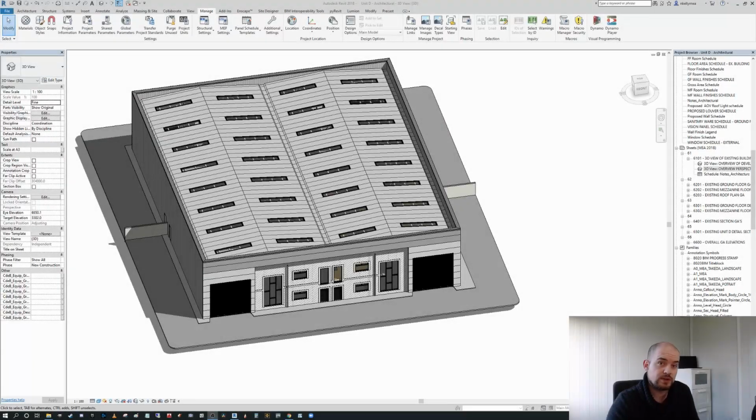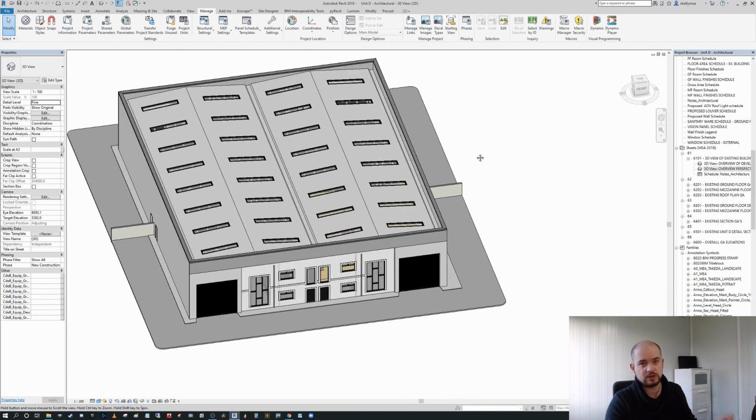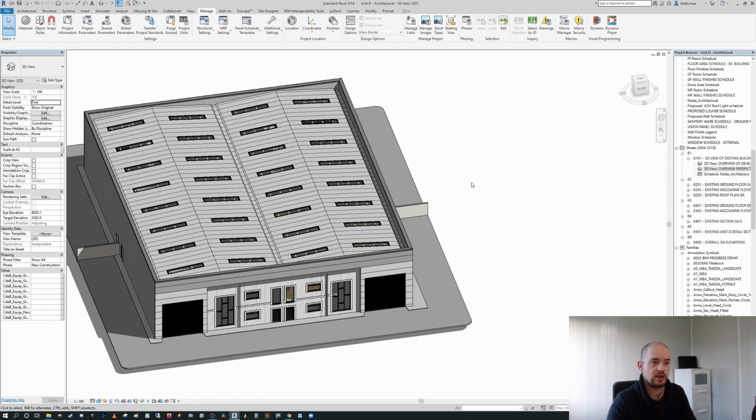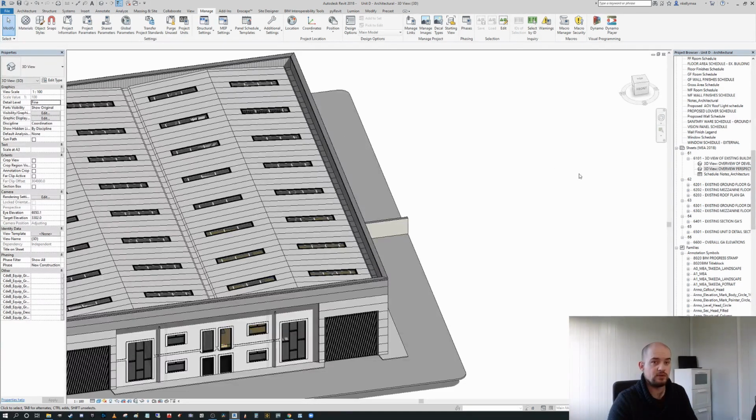Step 2, how to understand the directional drag selections of Revit. We all know that we can select by merely dragging a box in one way or the other. But I want to show you on screen here the difference between the directions of the drag and what they mean. If you drag from your top left to your bottom right, you get, by default anyway, this solid square. What this means is that this will allow you to select anything that falls within the overall boundary of what you're dragging. So the drag selection there, it's only elements.